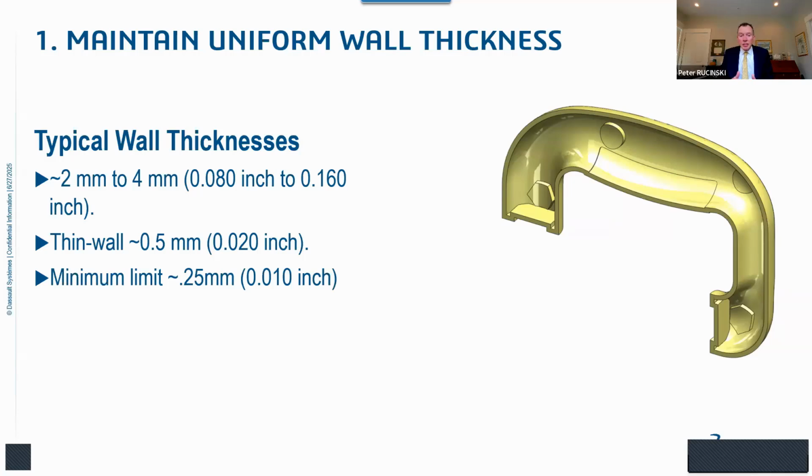That's because your cooling time will go up exponentially as part wall thickness increases. But again, on the other hand, I mentioned this earlier, for certain types of applications, you may need a thicker part for that geometry and material combination to meet your end use application requirements.